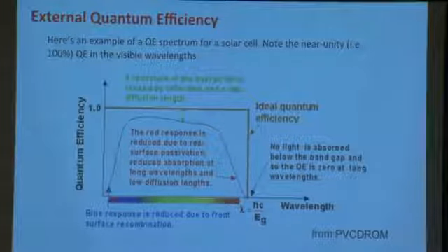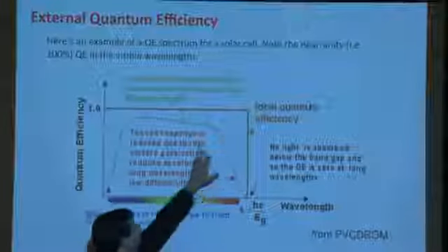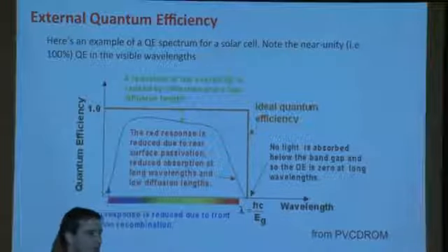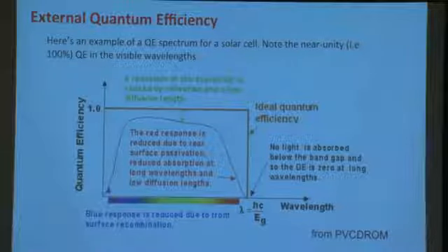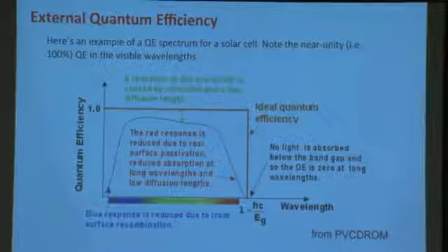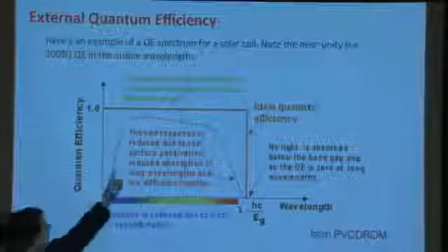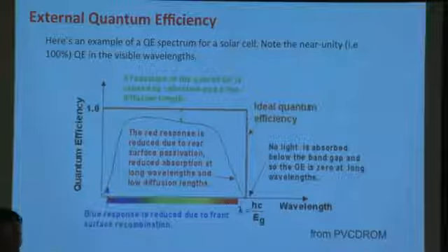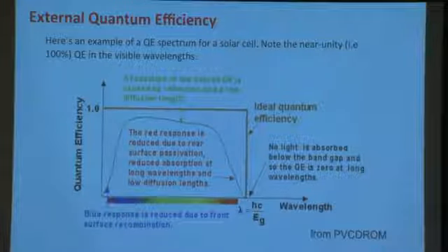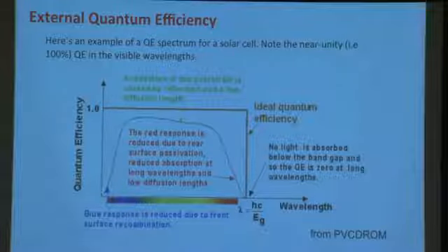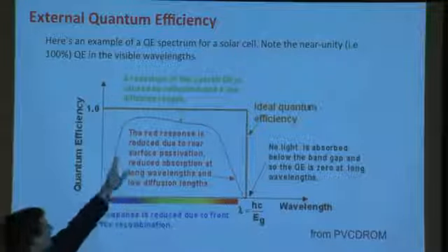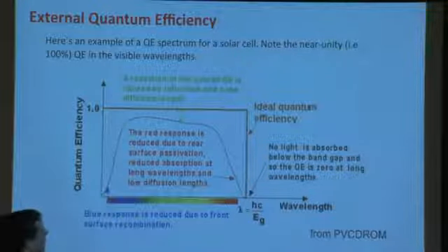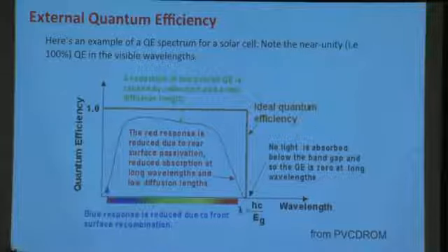Yeah, the absorption coefficient is dropping. And this light is starting to go straight through the device. There's a growing fraction of photons that are not being absorbed by the solar cell device. In the very short wavelengths right here, as I said before, oftentimes there's a dead layer right near the surface of the device that's impeding good electron-hole pair charge separation and eventually a collection.